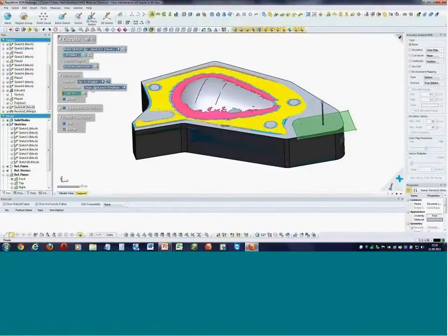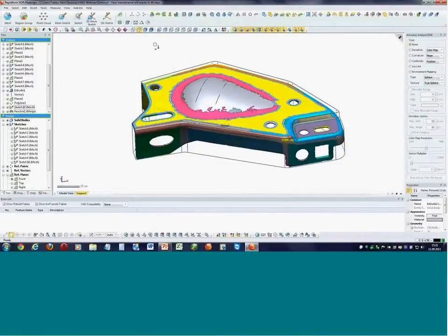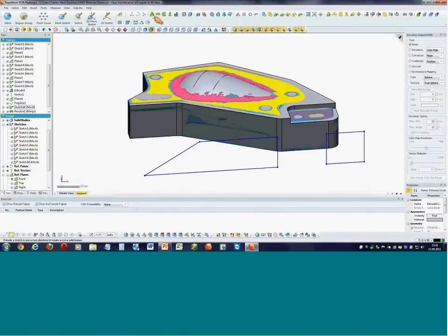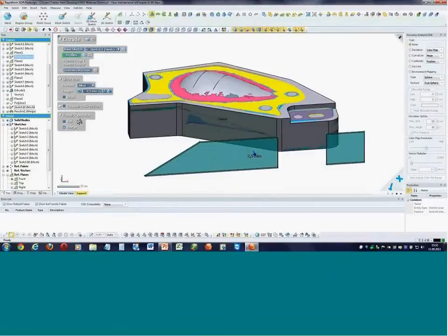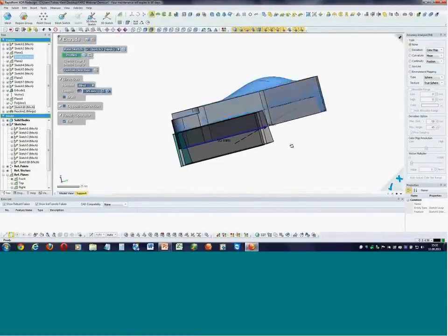Up to a region, trim with mean distance position, and I can select my region in the scan data directly. Then I can cut out this part from the scan data. That way I can complete my model in a few steps. Extrude a sketch which I created before and cut out this sketch from my scan data.